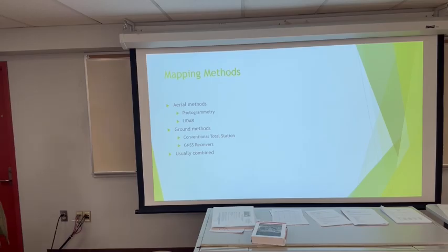Ground methods, we would have the conventional total station, GNSS receivers, as well as terrestrial-based LiDAR. A lot of people will even just refer to them as scanners. We have a SLAM scanner, which is one that you can carry and physically walk around and collect point cloud data as you are moving in real time. Usually, these two methods are combined.